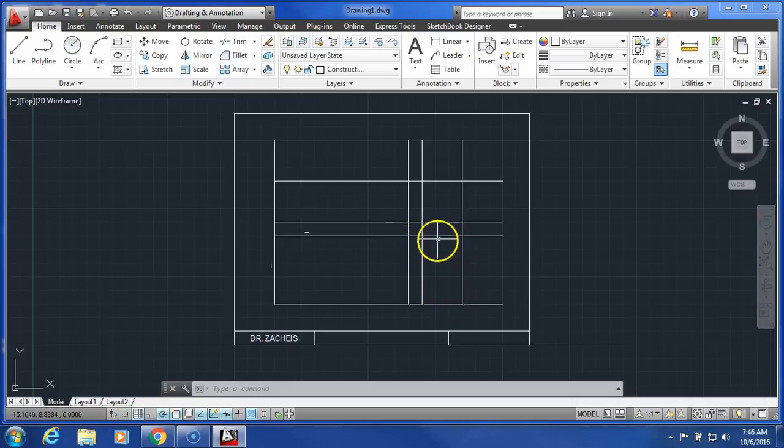Okay, it was already 2.5 tall. And then this one here, this is the top view. And again, we knew it was already at 5, but we had to make the width at 1.5. Okay, the front view and the top view widths will always be the same. They're always going to be 1.5. They don't get any bigger. All right, that's one thing to remember and keep in mind.